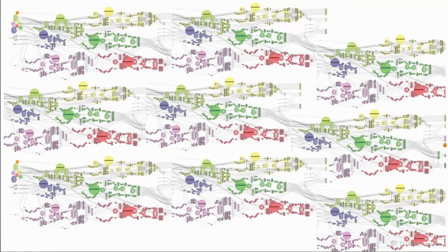On top of that, as the models grow in size, so do the Grasshopper definitions that created them. The larger the Grasshopper file, the harder it becomes to effectively manage it. So when dealing with incredibly large models and equally large Grasshopper definitions, you need a way to dissect the process.